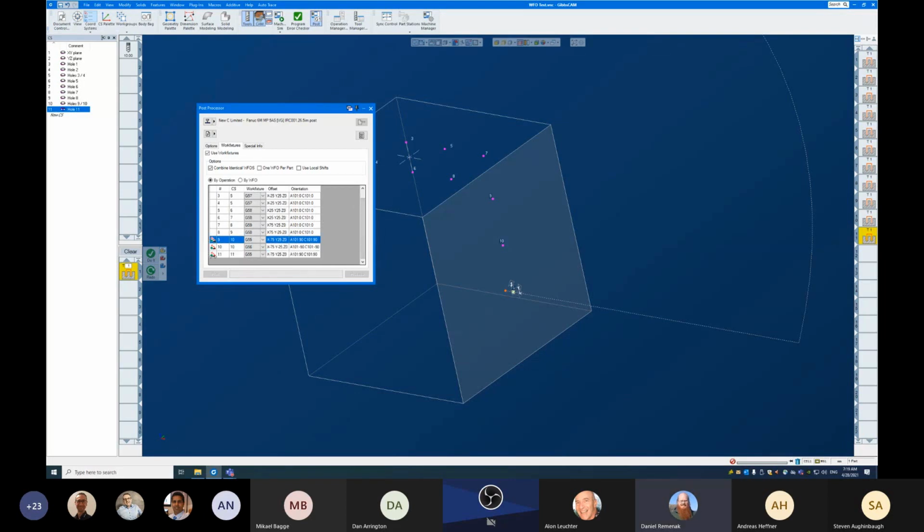Now we can still see these icons here. Again, this one on the right means that we're at a different orientation than was specified by the selected work fixture. This is wrong in these two cases. This one means that we've picked one by hand. That's correct. We have picked these 3 by hand. And in fact, if we picked another one, we could say, I want hole 8 to be done in hole 7's work fixture. We can see that this one has now been selected by hand. It has been overridden by the user.